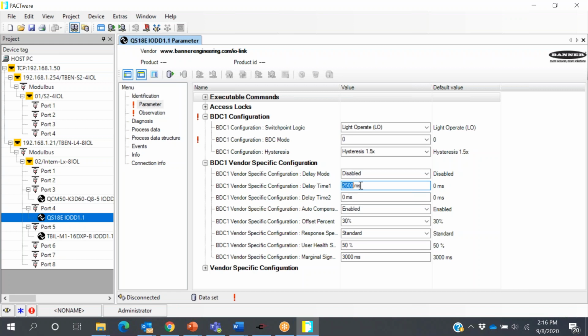So again, taking my single USB master, I can connect to the sensor, open the same software I was just showing you, go in and set the 4 milliamps for, I don't know, 50 degrees C and 20 milliamps for 200 degrees C. You can also do it in Fahrenheit. And I can set a switch point for like 100 degrees. Once I've set that up, I can go disconnect it from my laptop and just go put it into a 4 to 20 milliamp application, PNP switch point type application.